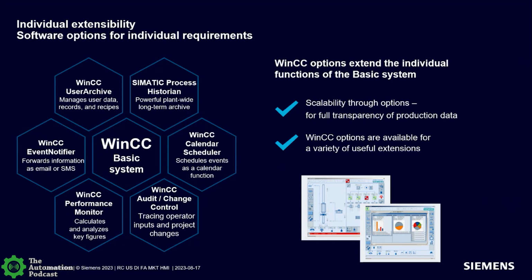Process Historian is an off-site historical repository. It can pull information from various different WinCC systems as well as our PCS systems and pull them all into one central location and store the data that way. So if you need off-site data retention, that's one way you could do it, or just use the standard WinCC Historian, pulling the database and keeping it in the WinCC system.